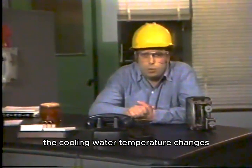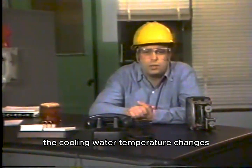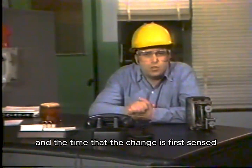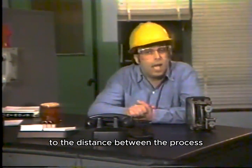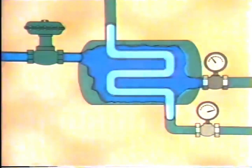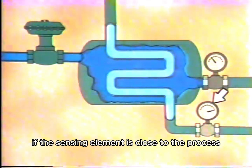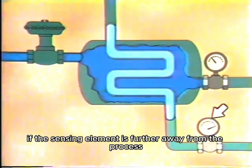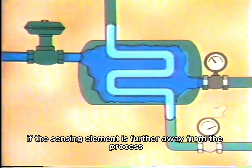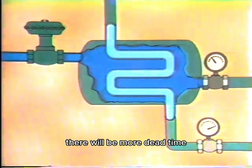Dead time in the heat exchanger process is the delay that occurs between the time the cooling water temperature changes and the time that the change is first sensed. It is directly related to the distance between the process and the sensing element. For example, if the sensing element is close to the process, there should be very little dead time. If the sensing element is further away from the process, there will be more dead time.